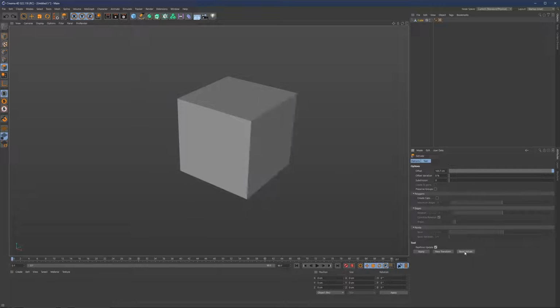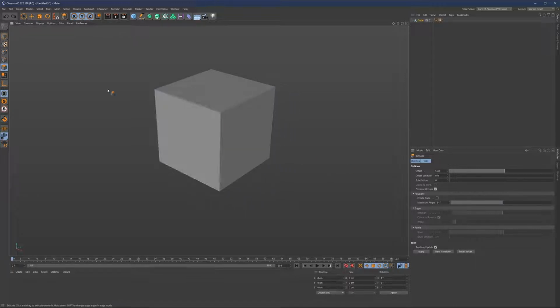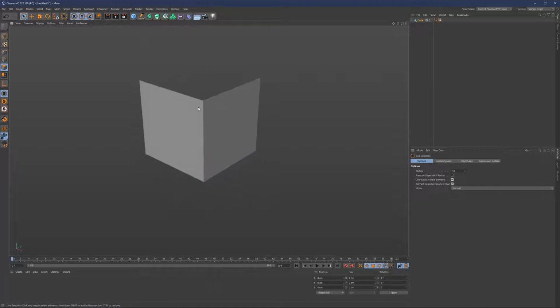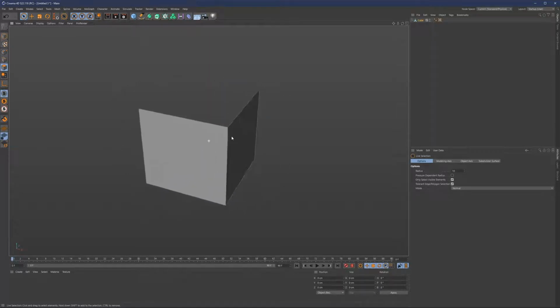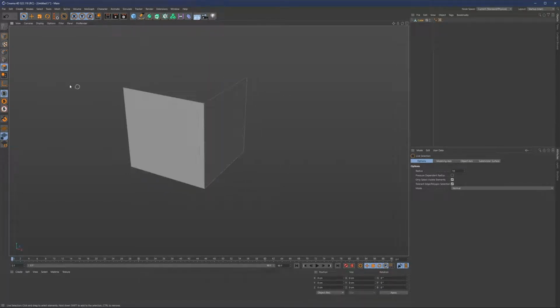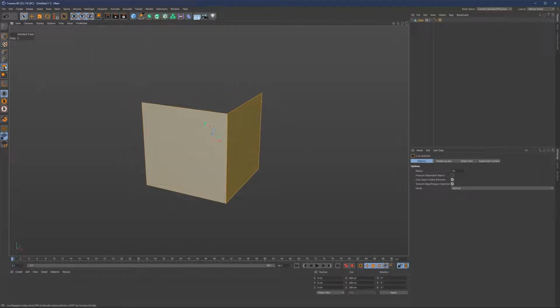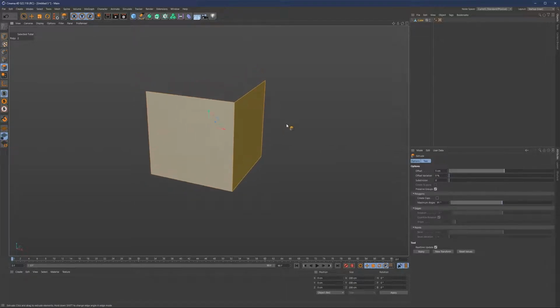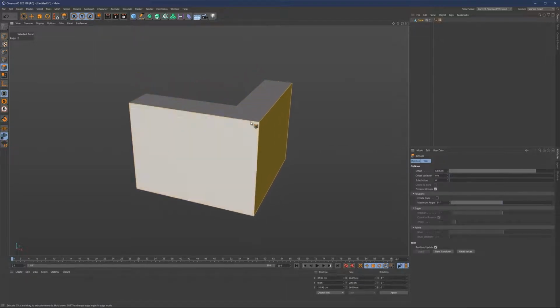This is also something that we're going to use often, and to demonstrate, let's just select these two faces. I'm going to hit V, go to select, and then invert, delete, and then we have only these two faces like so. And let's now go to selection, polygon selection, select both of them, hit D again for extrude, and now simply extrude the faces like this.